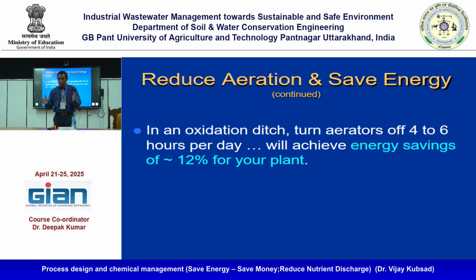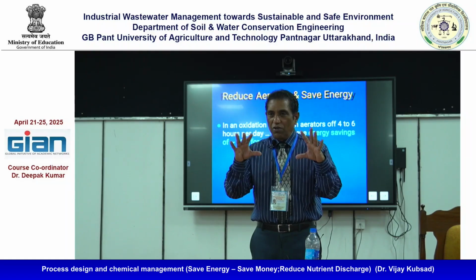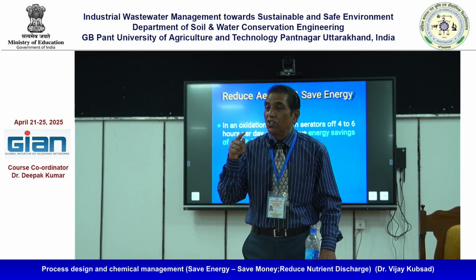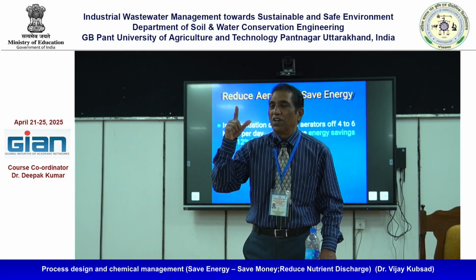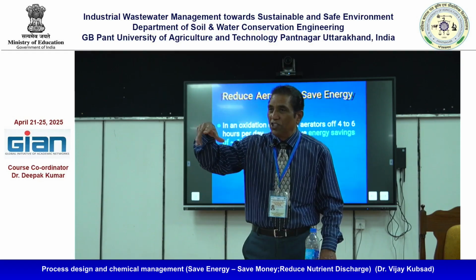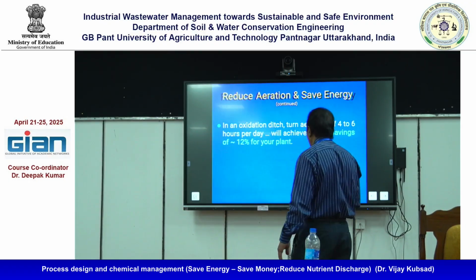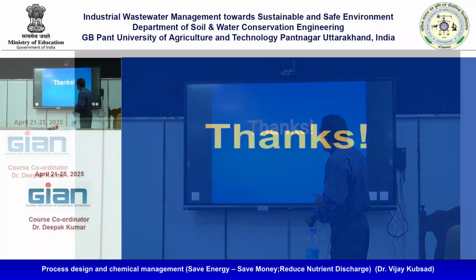Right? If there is a variation within a day, an hourly variation, you can keep the aerator on, and once the oxygen level goes up, you can switch it off. This aerator is a big consumption. That is why other biological processes are evolving to reduce this cost. You can imagine, if you have a big pond with a number of aerators, how much the energy is. Energy cost is enormous. So it is important to look at the economics once you achieve the quality.